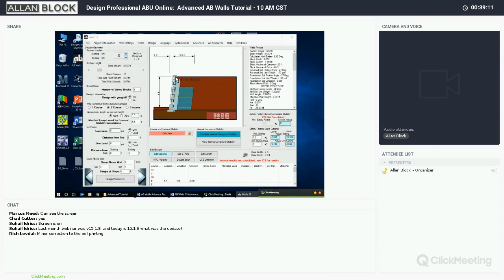If I try to do another layer of GeoGrid, again, spacing is highlighted. I click on that course that has grid. Now all of a sudden, I've got 6 courses that are unreinforced. I've got my upper and lower structures. Lower structure looks great, but now I've got problems with my upper structure. I can't have 6 courses of block without some type of reinforcement.